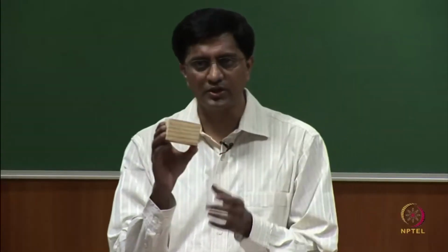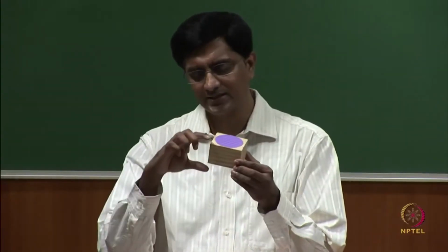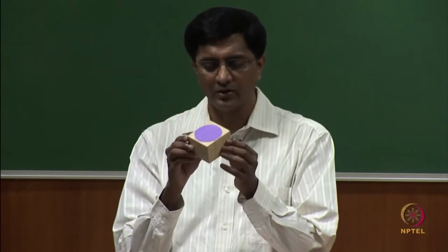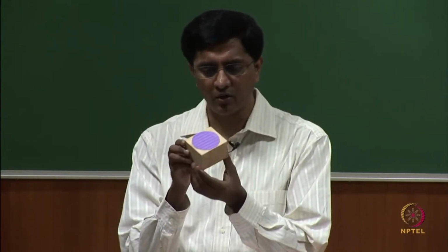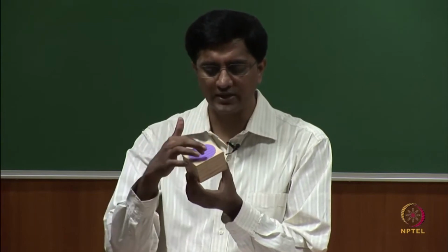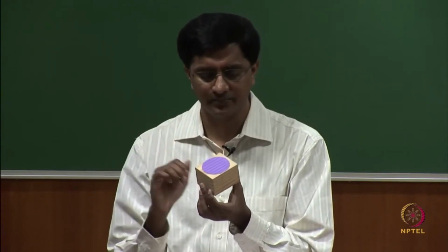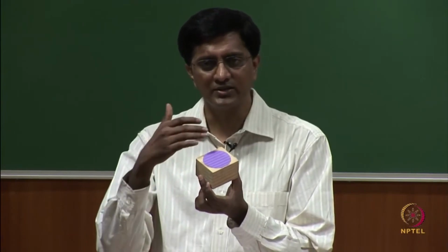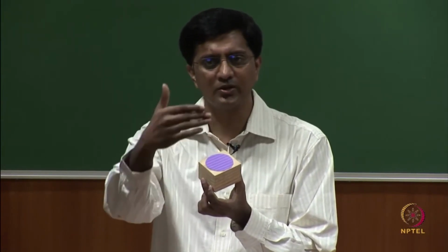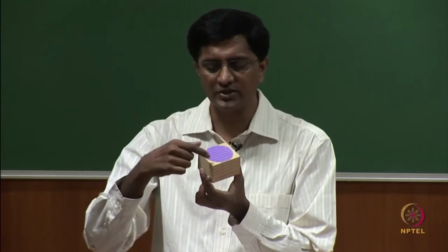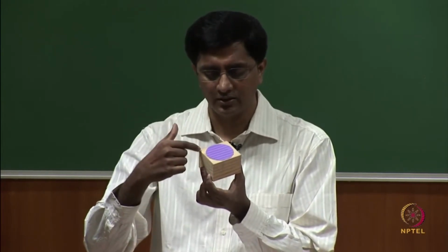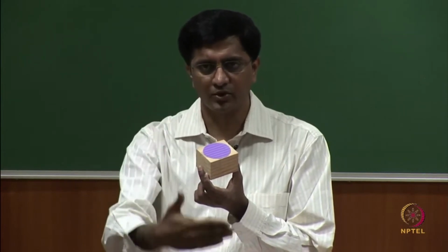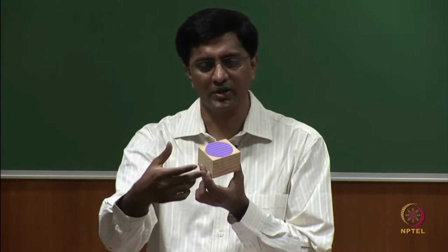So, let us focus on this cube. Let us say each side of the cube is of 1 unit. We said for isometric drawing, we are orienting the cube in such a way that we can see all the 3 faces, fine. Now, let us focus on which of these lengths will be captured as true length on the projection plane. So, for example, this edge, if it is projected on the projection plane, will it be captured as true length?